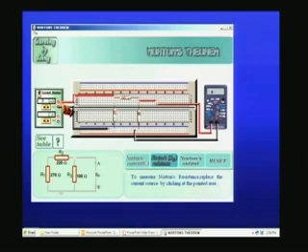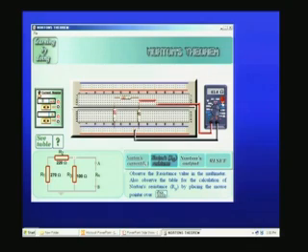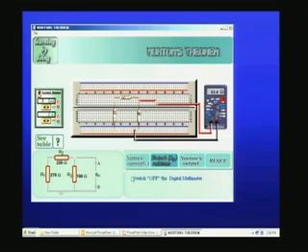Now we have to obtain the Norton's equivalent resistance. For that, if I have a current source, I should open circuit it. Therefore, when I click here, the connection to the current source is removed. That means it is open circuit here, and I just have the 3 resistors, and I should make use of the multimeter in resistance mode and measure the resistance. Let me switch on the multimeter. It comes in ohms range, and it is measuring 83.4 ohms. So this is the Norton's equivalent resistance. Rn is actually R3 in parallel with R1 and R2, and therefore the equivalent resistance is 83.4 ohms.